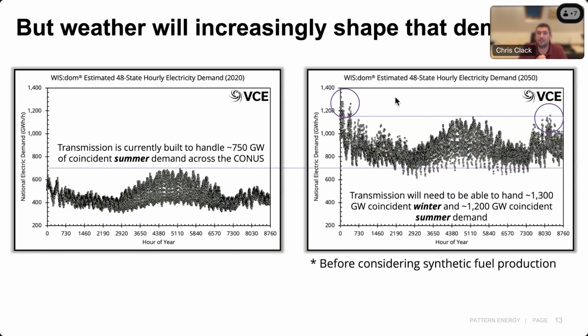Even if electrification isn't there, the supply is going to change quite dramatically, which makes the supply itself more volatile. But all I'm trying to show here is that basically when we model this out to 2050, if we put electrification in, essentially all load is above today's historical peaks. And we see some really big spikes happening when we electrify. And that's both because we've got supply coming in, but the main reason is that we have these really difficult periods where we're either heating houses when they're cold, or we don't have the battery storage to minimize these peaks.